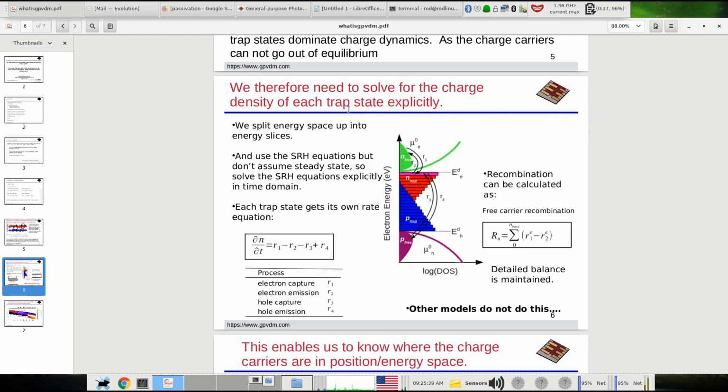And it's a very interesting technique because it can tell you things about recombination, the density of states, and sort of how efficient your device is at emitting light. You can learn quite a lot of information from photoluminescence. So what we're going to do is use gpvdm to simulate PL, effectively simulate it being pumped with a laser, and then watch the spectrum of photons that are emitted from the device.